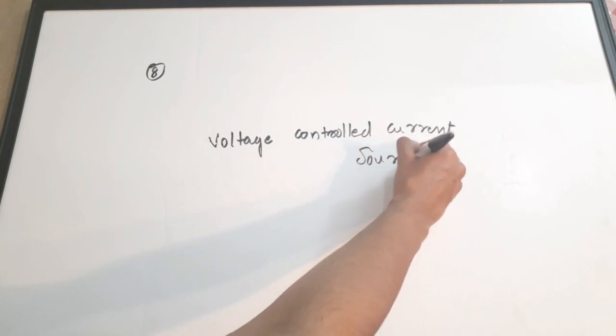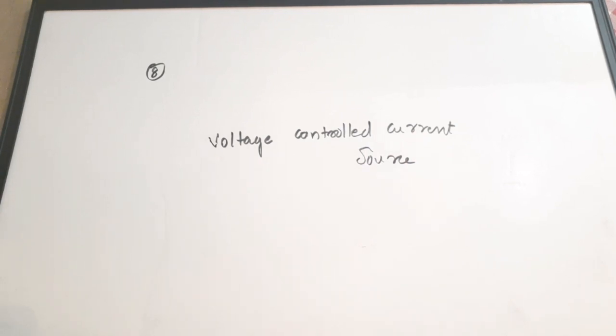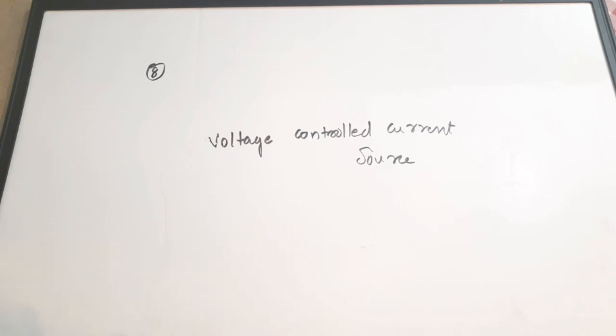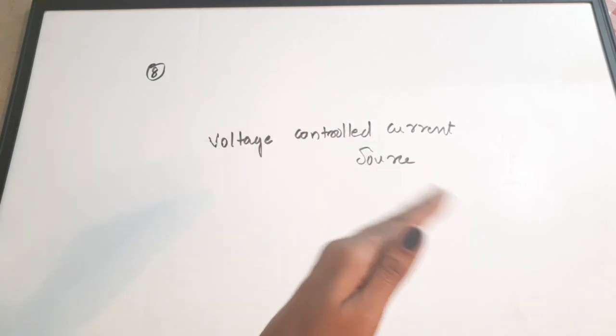So we all know that JFETs or FETs in general are field effect transistors, or they are voltage control devices. So the output current IDS or ID, for the case of a JFET, is controlled by the VGS, or the voltage you apply on the gate source terminal generally. So it is a voltage control device.